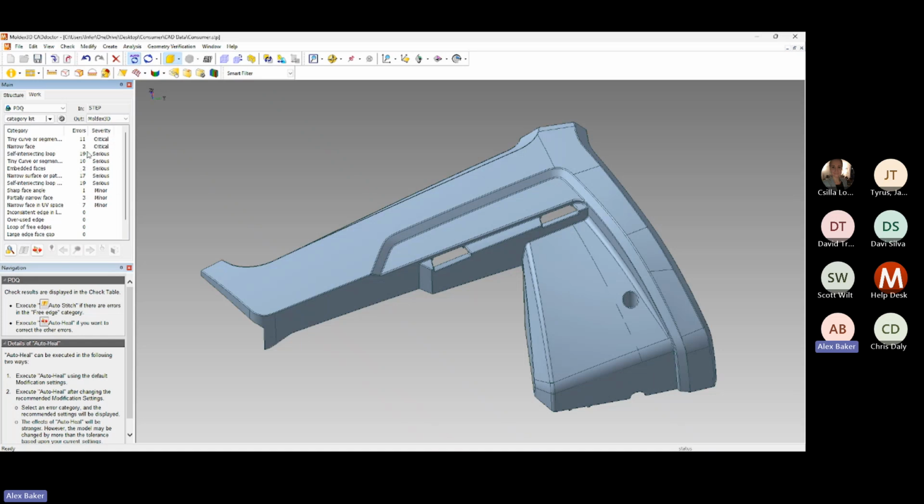We don't like to spend too much time on fixing in CAD Doctor, just because any manual effort spent in CAD Doctor isn't necessarily going to translate to a saving of time in Studio. And that's really what we use CAD Doctor for, to save any frustration and any effort required to fix the surface mesh. We want that surface mesh to be automatic, so fixing a lot of these errors really helps us to do that. But if we have to spend a lot of time in order to prevent those errors, then it's not really worth it for us.